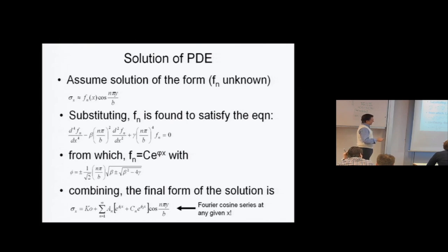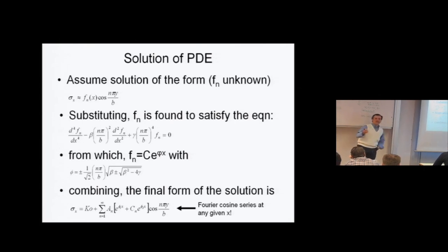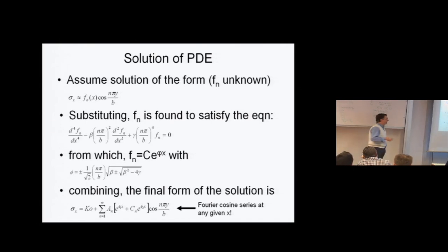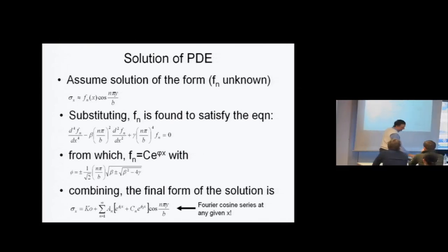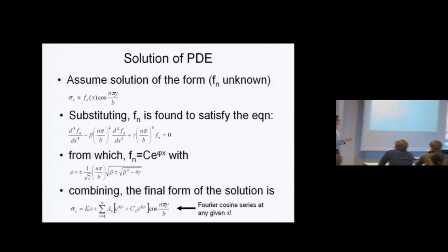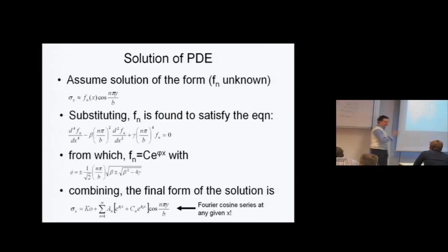If I just take this now blindly and I combine with my expression here and recognize that this n, which appears there, can be any integer, then it becomes an infinite series. So I will have this form to represent this, plus a constant, because this constant k0 also satisfies my equation if the stress was k0, and because these are all derivatives, obviously the constant will disappear.